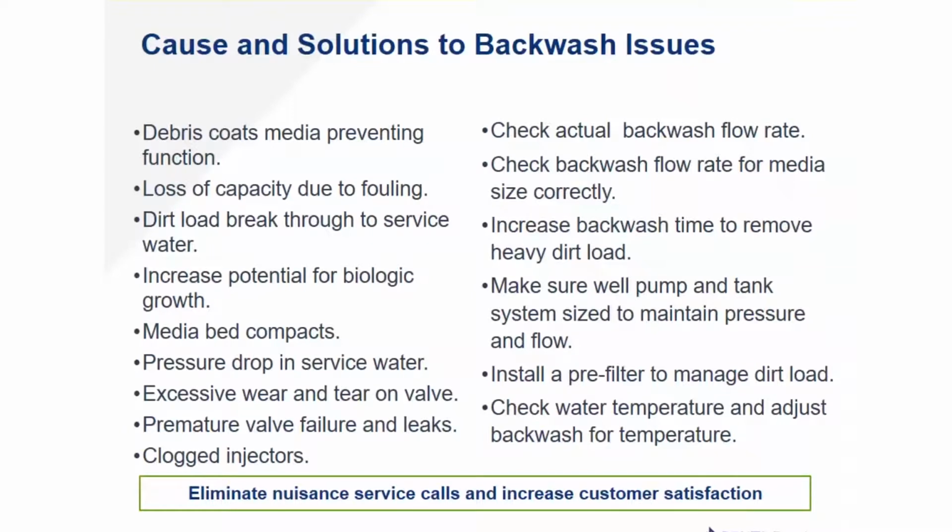Media beds will compact. Just saw a picture of this online this week in a group where someone had filled a 1 cubic foot tank completely full with green sand, and the unit had to be cut apart to be serviced and removed. No freeboard, no expansion, failed media, not doing the job we wanted it to. Pressure drop in service water. Why? Because we're getting a filter cake built up on the bed that resists flow. We're just basically straining out more and more debris the tighter we get dirt loaded in a filter.